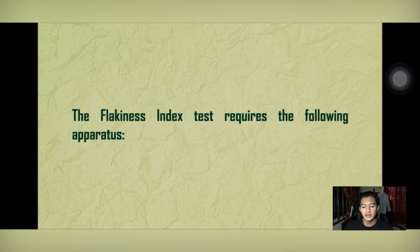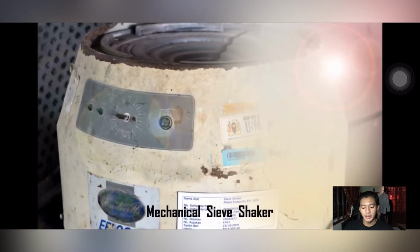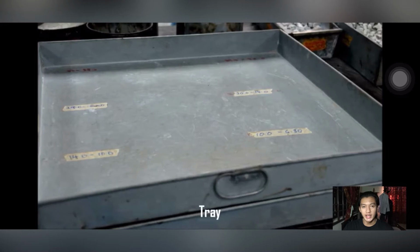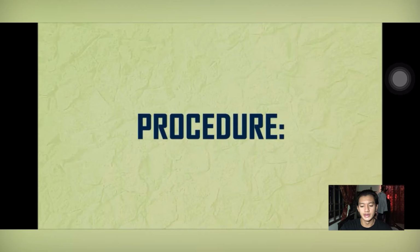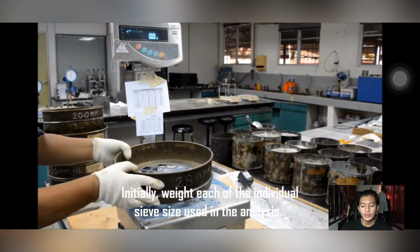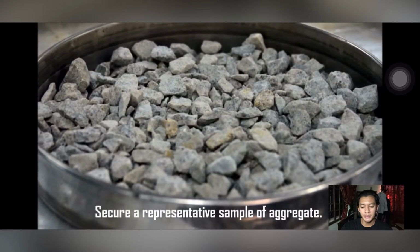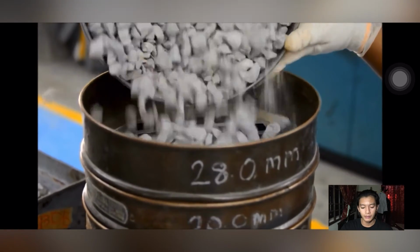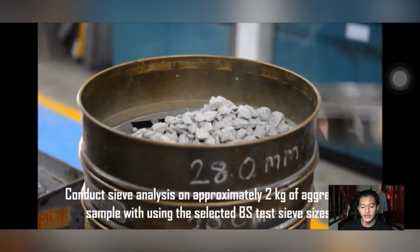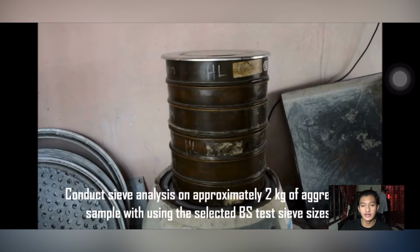The flakiness index test requires the following apparatus: thickness gauge, a BS test sieve, mechanical sieve shaker, tray, and balance. Procedure: initially weigh each of the individual sieve size used in the analysis. Secure a representative sample of aggregate. Conduct sieve analysis on approximately 2 kg of aggregate sample with using the selected BS test sieve size.